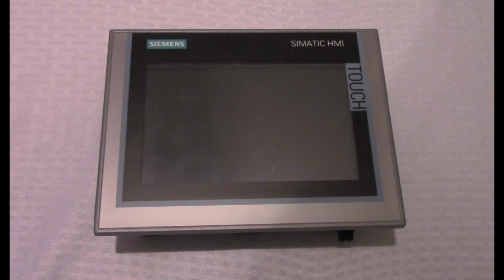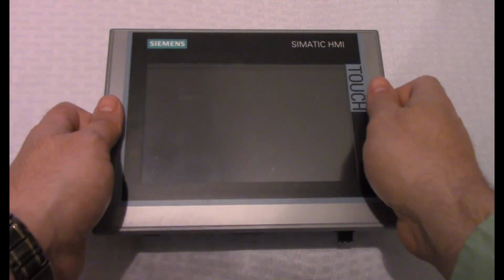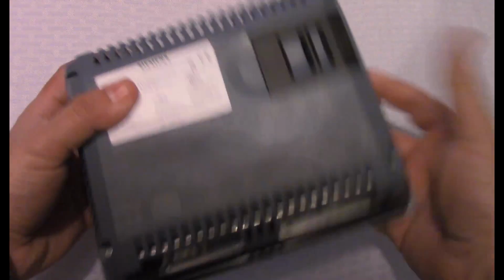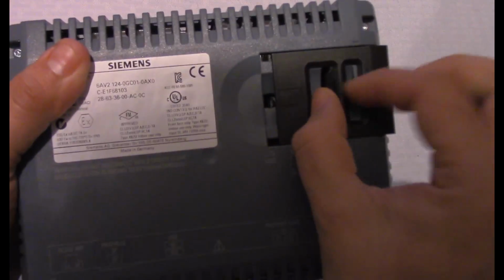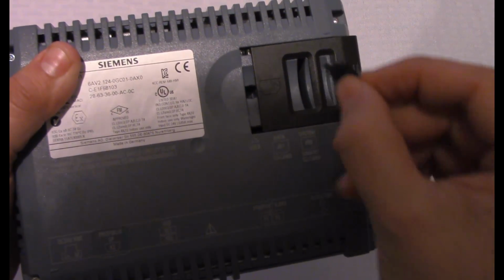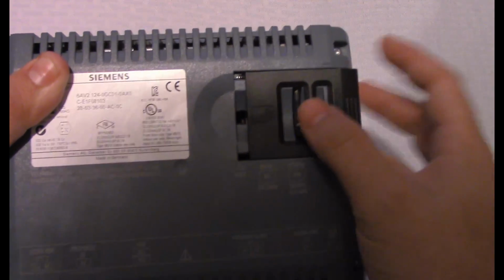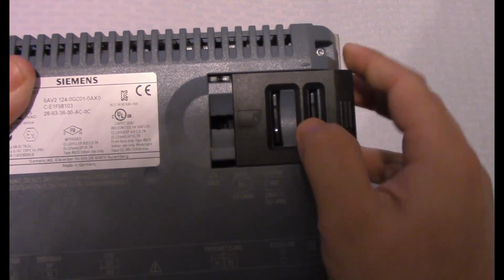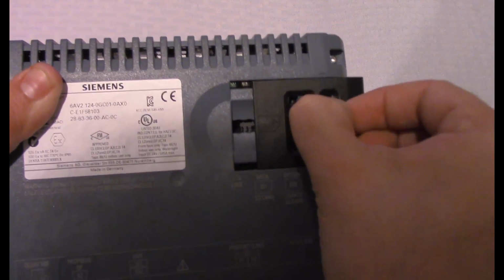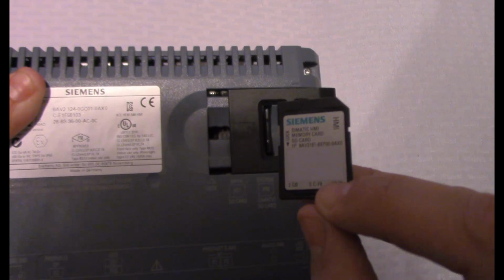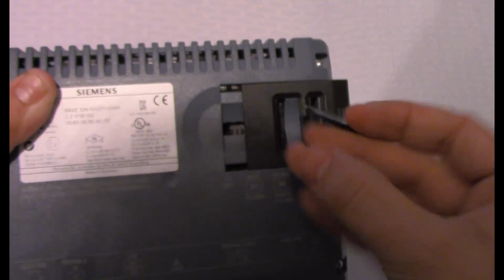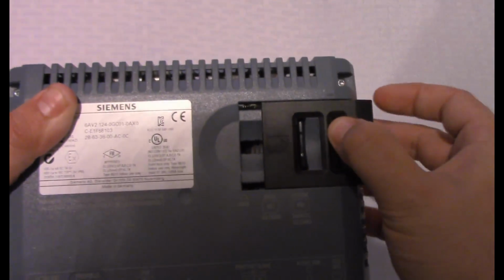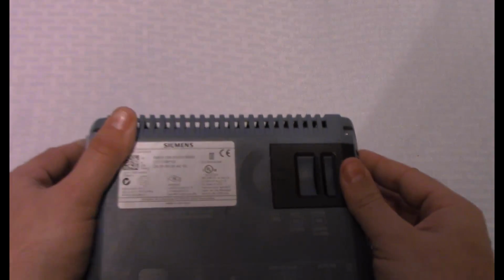The Comfort Panel also has its own way of automatically backing up its data, screens, and so forth. On the back of the Comfort Panel exists two SD card slots. The first slot is for data, and the card that can go in here can be any standard SD card. The next slot is for your system backup, and this can only be a Simatic HMI memory card that has a capacity of 2 GB or higher. Neither card is required for operation of the Comfort Panel, but it is recommended that you use the system slot to automatically back up your HMI screens.